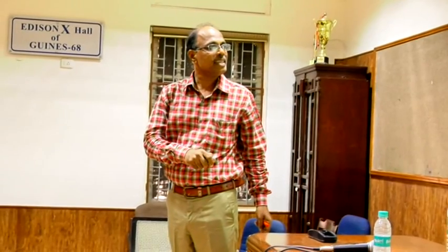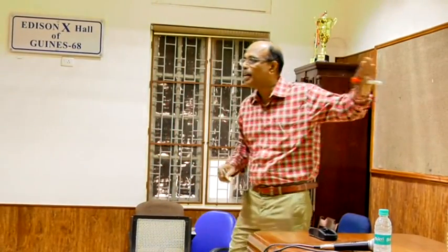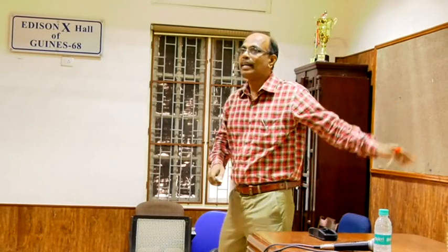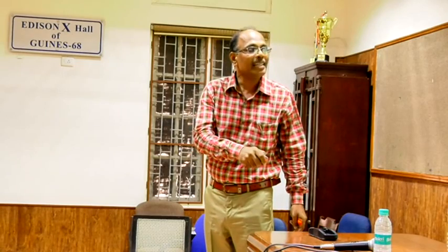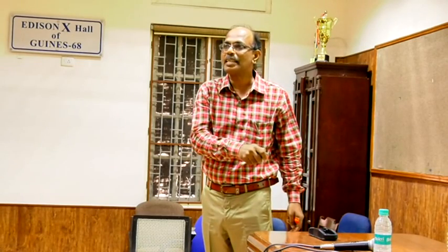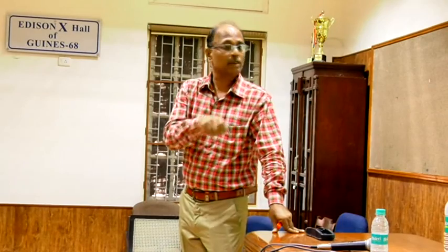The difference, this equation minus this, should be equal to 0. So the problem here is to find the values of V's and deltas that will make the mismatch 0. This minus this should be 0. So the problem for this part is to find the values of V's and deltas that will satisfy all the 12 equations.